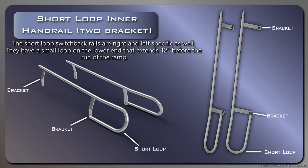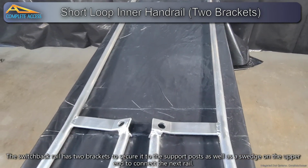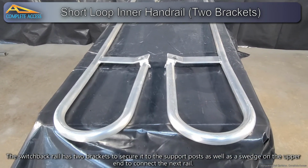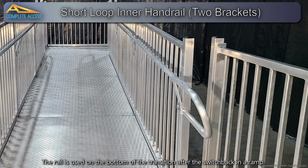The short loop switchback rails are right and left specific as well. They have a small loop on the lower end that extends 12 inches before the run of the ramp. The switchback rail has 2 brackets to secure it to the tops of the legs, as well as a swedge on the upper end to connect to the next rail. This rail is used on the outside bottom of a ramp run leading to a switchback.